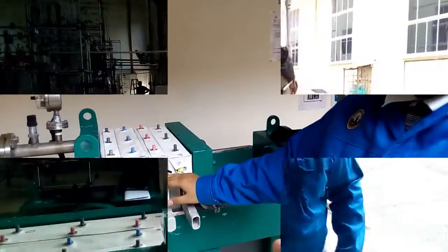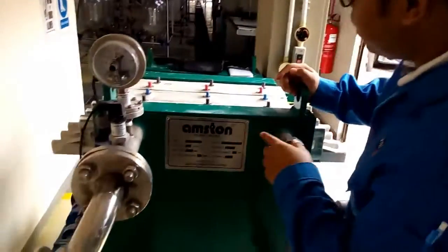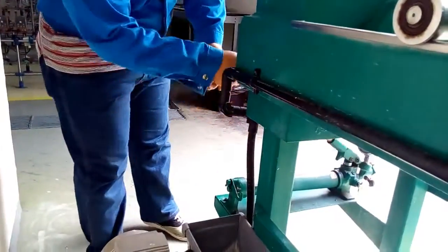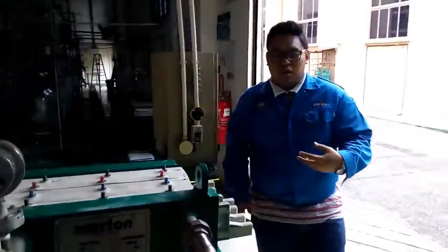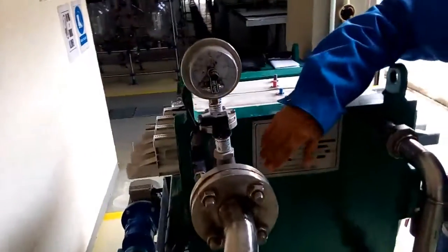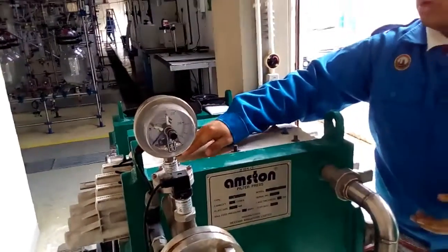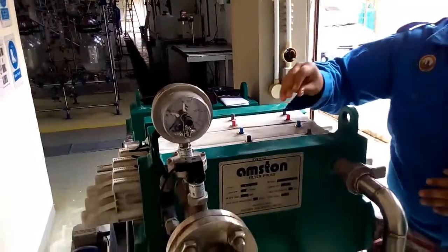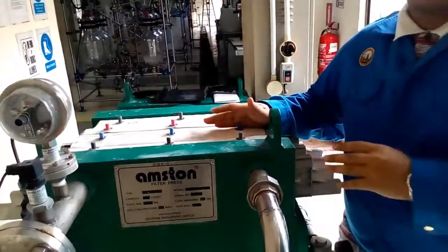Stop. From the start earlier, before that, we adjusted the pump to 4000 psi. If you can see there, this is the pump we adjusted before. So we adjusted it to 4000 psi, so the water pressure will be higher so that it can flow at a fast velocity. So this is the pressure that limits the pressure for the water flow through the filter frame.